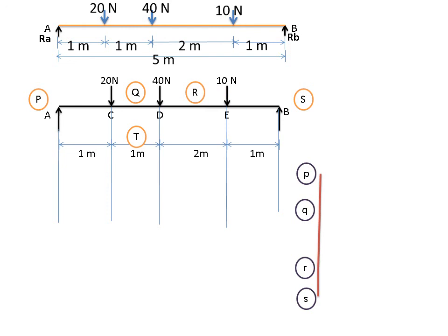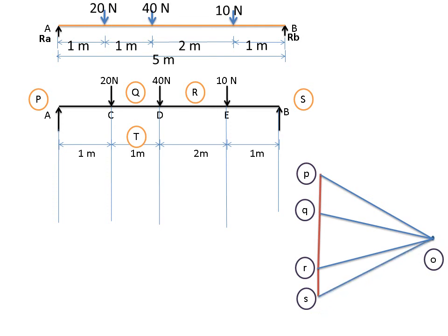Now somewhere here you draw a point. Anywhere, call it as point O. Now join all these points to O. So first PO, second QO, third RO, and fourth SO. Now take PO. Parallel to PO, draw the first line here. The name will be given PO. Second, parallel to QO. This is QO. Shift it here, from this point draw a line parallel to QO. Then parallel to RO, draw a line here, RO. Similarly, parallel to SO, draw a parallel line here. So this will be called SO.